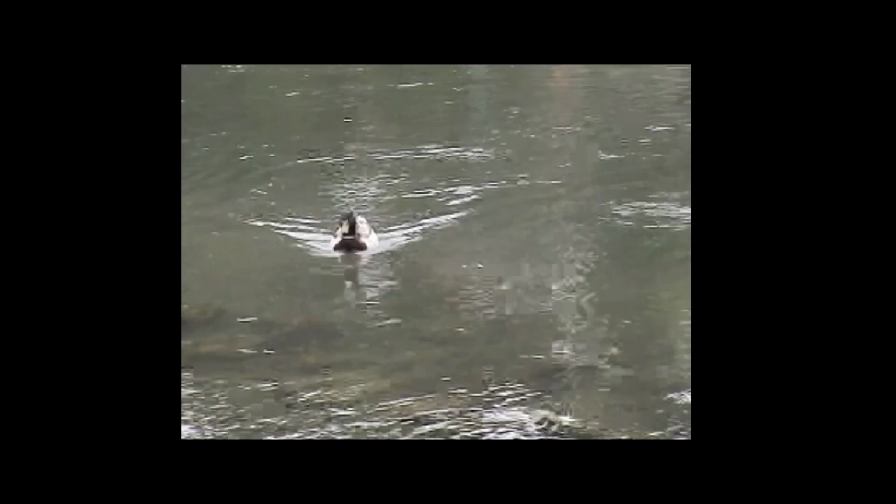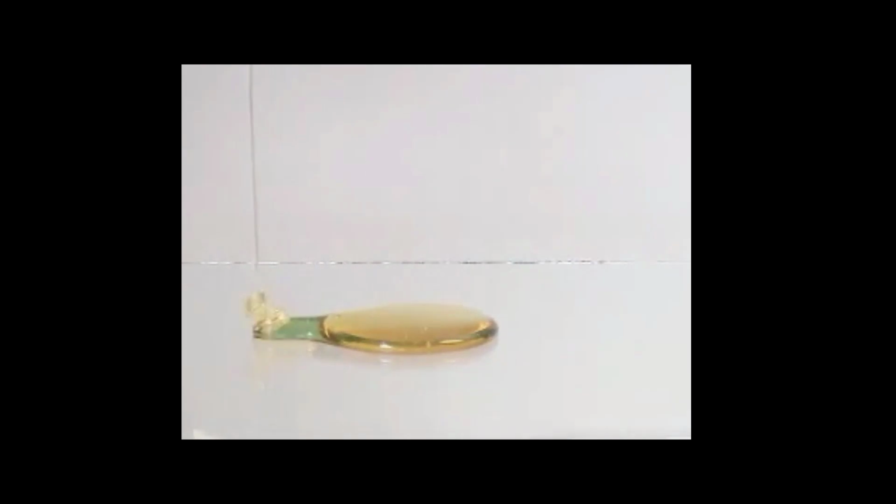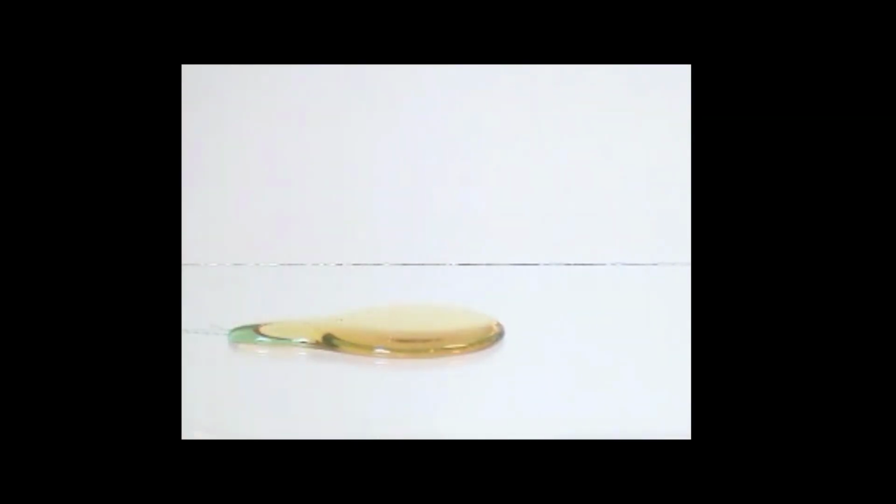Fluid properties are usually treated as continuous functions of position in a flow field, since their variations are quite uniform. For example, we don't usually think of flowing honey as being composed of individual molecules. This differs from the approach of basic kinematics, where the trajectories of individual particles or systems are studied. To analyze fluid mechanics problems, we most often use an Eulerian frame of reference, where we observe a fixed flow field rather than following individual moving fluid elements. In this Eulerian method, we study the properties of the flow pattern in terms of spatial position and time.